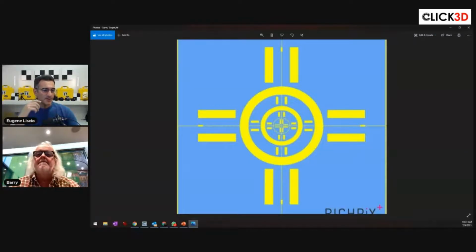So what do you normally print these out on? Well, I've used all sorts of different things, to be honest. So I've just printed them out on business card, and sometimes I printed them out and laminated them. Some people have a little bit of a problem with lamination, getting a total reflection on the total station reading. Hmm. I've never really found that. I have actually put little dots with reflective tape in the middle, little circles of reflective tape. You get a punch and put that right in the center. But generally speaking, a matte surface is great, and then a lot of labeling stock is fine.